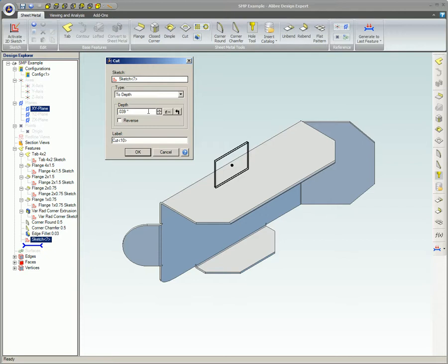If you need to use the material thickness, but it's not shown in the box, click the return arrow icon to place the material thickness value in the box. Through All cuts through all solids starting at the sketch plane, cutting in both directions. Midplane cuts to depth equal distances in both directions from the working plane. The length you specify is the total length of the extrusion.